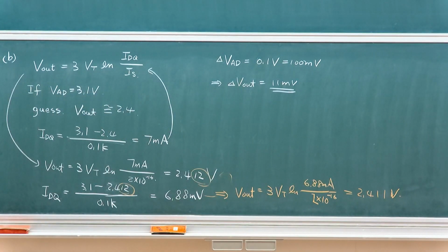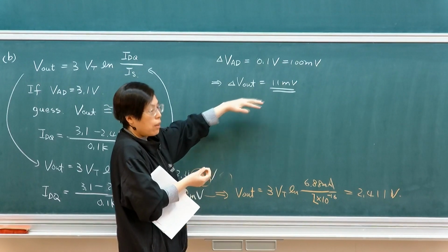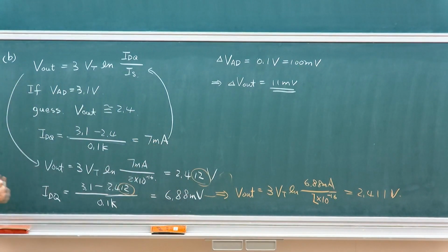So this is very effective as to what it is designed to achieve. This regulator circuit, as I said, is designed to make sure that even though my input changes by 100 millivolt, it will attenuate the response at your output node. So it will make it less sensitive to the fluctuation on your adapter output. So that's the whole purpose of having a regulator circuit.